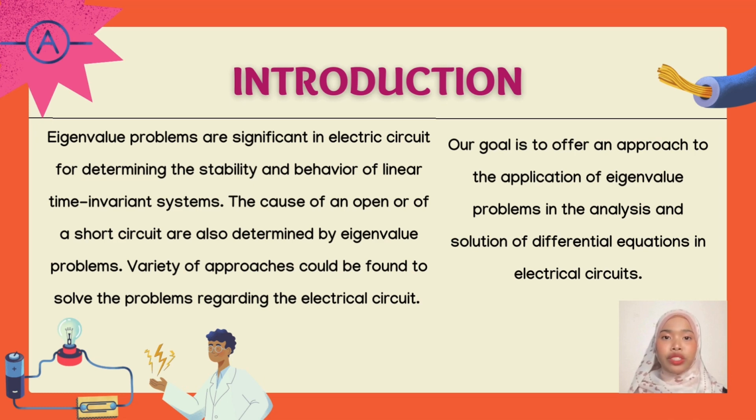Eigenvalues are used to determine the stability and behavior of linear time invariant systems such as electrical circuits. The stability concept is necessary for the dynamics of circuits. For stability, all eigenvalues of circuits must be located on the left-hand side of the complex S-plane. In general, the eigenvalues of circuits are obtained from the coefficient matrix relating to the state equations in the time domain in circuit analysis courses.